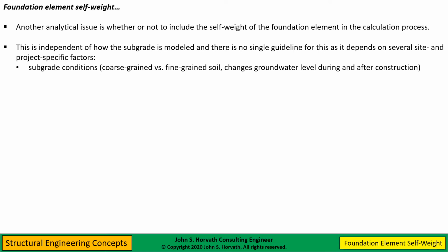The subgrade condition, certainly if you're dealing with a fine grained soil where you have time dependent effects, you need to consider immediate loading versus long-term loading after consolidation or reconsolidation has occurred. And also changes in groundwater level, because very often the weight of the foundation element, a mat foundation, for example, will be used to resist groundwater pressures.